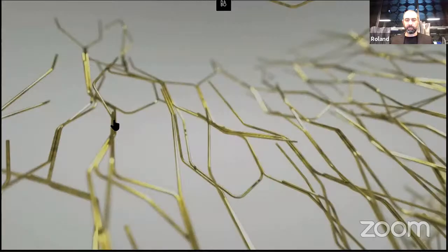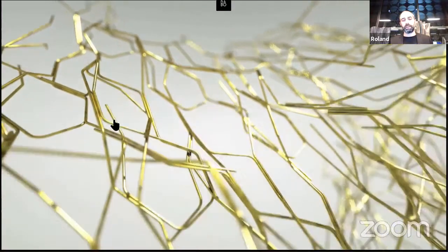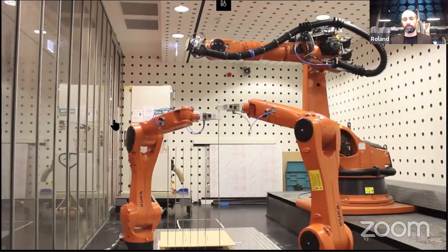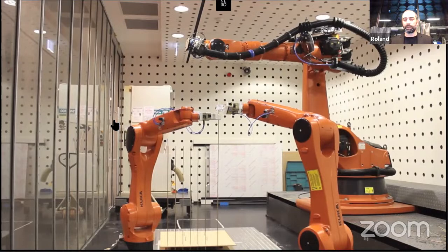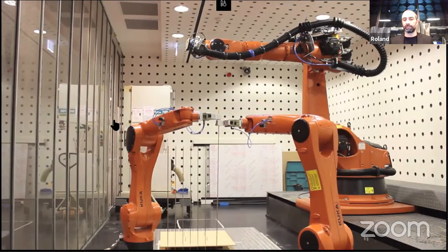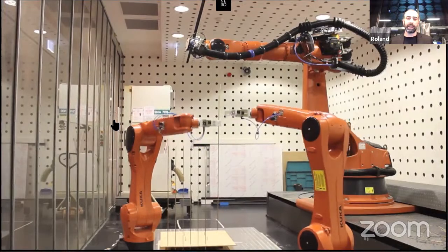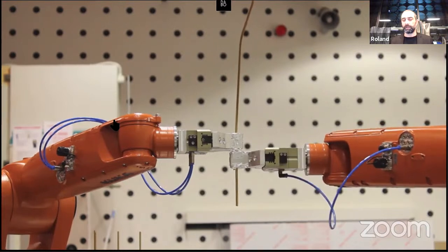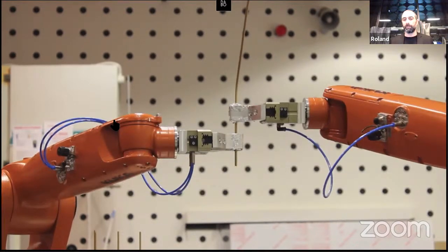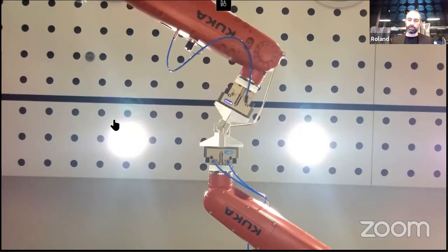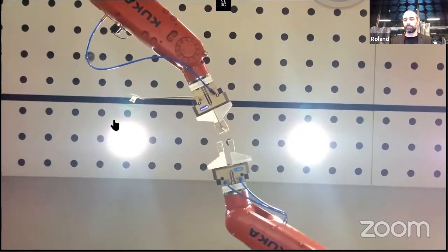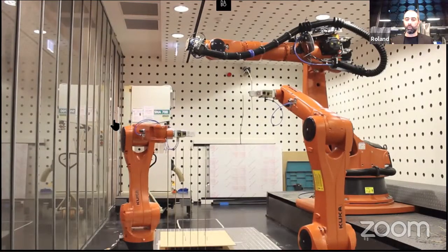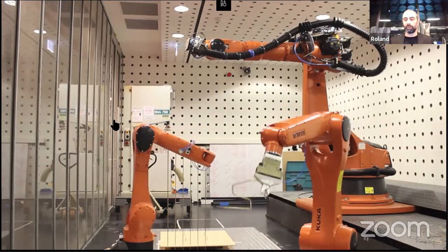One important aspect of this project for us was that the underlying generative algorithms we're using are inherently highly volatile. They're wild algorithms, and they make complex structures which are very hard to post-rationalize. So we needed to understand exactly how the robots would bend these parts, what the limitations were, how far they could bend, what sequence of bends they could do before the rod would hit itself, how far apart those bends could be, and then program all those constraints into the generative algorithm. The ambition was that the algorithm would create these wild structures, all within the limitations of what is possible in terms of fabrication.